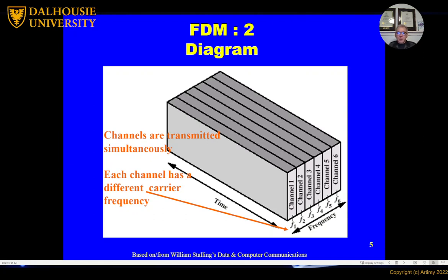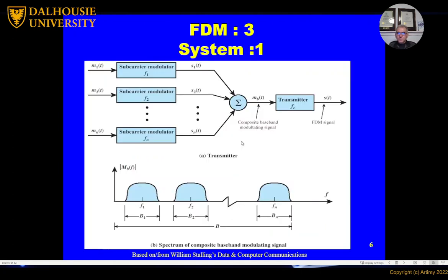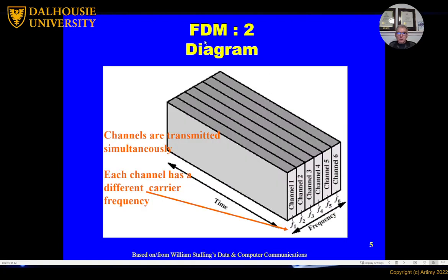We have 6 megabits of bandwidth available in the link. So we chop that into 1 meg, 1 meg, 1 meg smaller channels and allocate each one of these 1 megs to a pair. Right? So that's how we do what we call frequency division multiplexing, FDM.